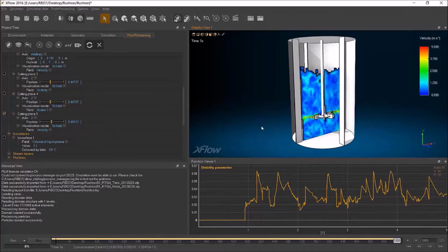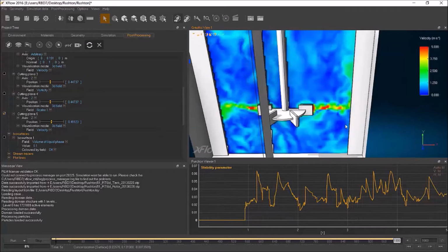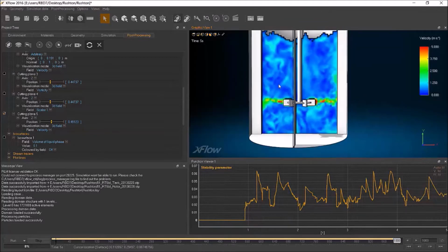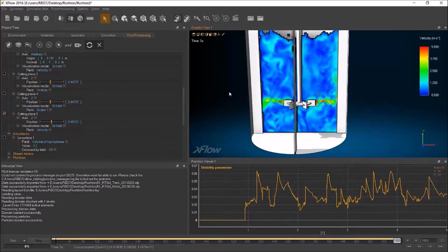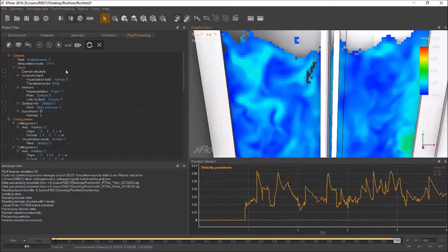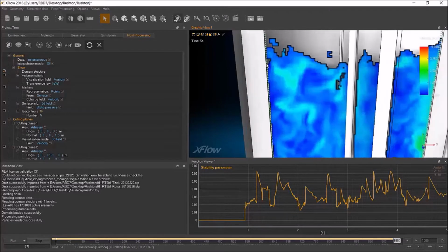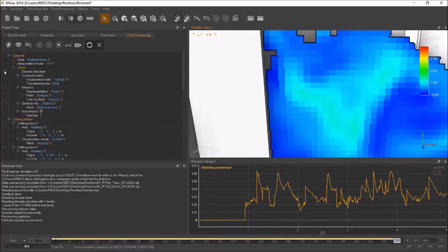So when you see the velocity here, it's actually showing higher velocities on the outlet, on the blade tip, and is sort of propelling out in the radial direction the flow here. And you can see all the mixing as well here. We've got the voxelization due to the lattice structure that you can smoother using interpolation as well, which is basically just interpolating data. This is due to the lattice resolution in that case, which you can see also you can plot with the domain structure and see the distance between two lattice points in that case.